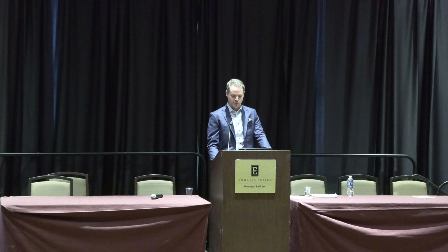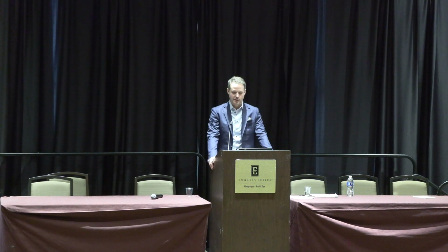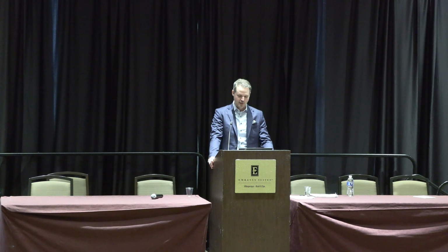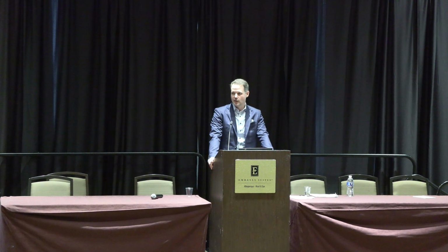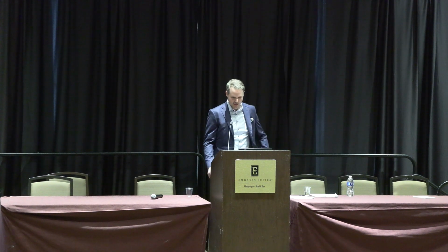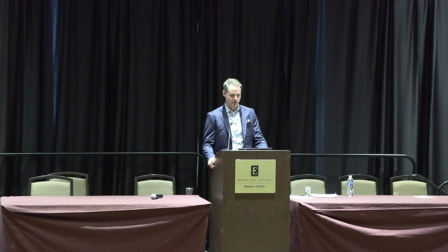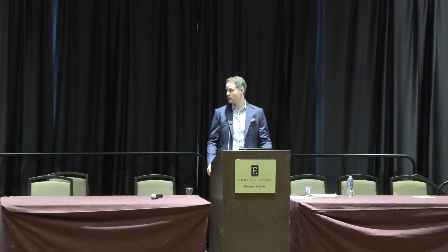This equipment can do a full spherical scan with its 256 beams, so it'll generate point cloud data with millions of unique XYZ points. It can be connected to motion compensation and a total station to be fully geo-referenced and not just referenced to an arbitrary datum, which we did for this project. Since what we were trying to see was located at the base of the piers, we actually had to fabricate a special low-profile plate mount so it would sit right on the channel bottom in order to gather the data that we wanted. We also combined the sonar data with above-water photogrammetry to create a fully realistic 3D model of each pier that we were investigating.